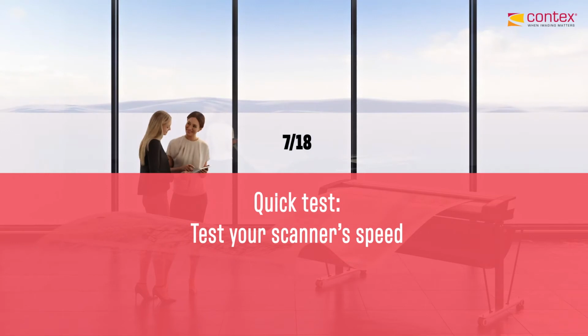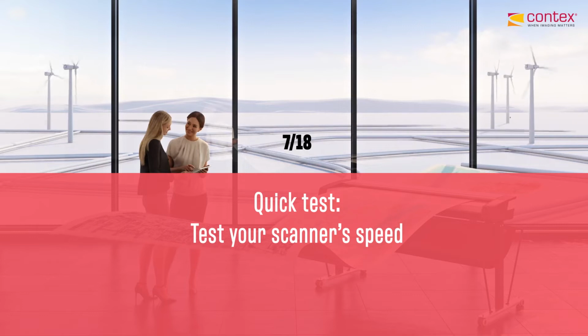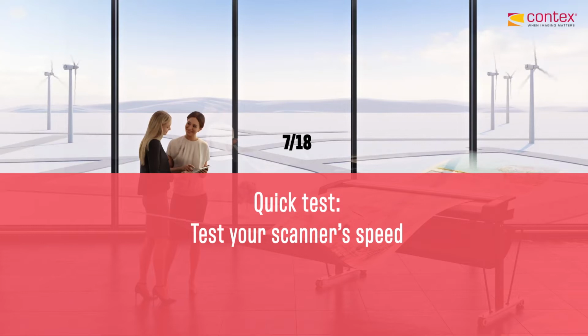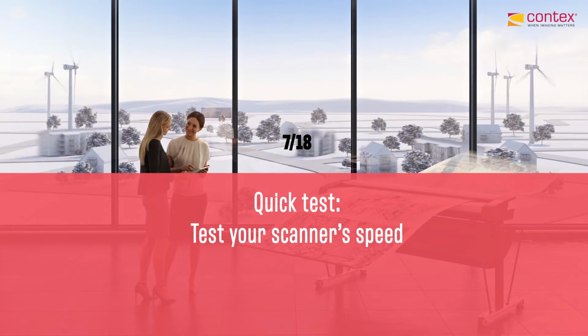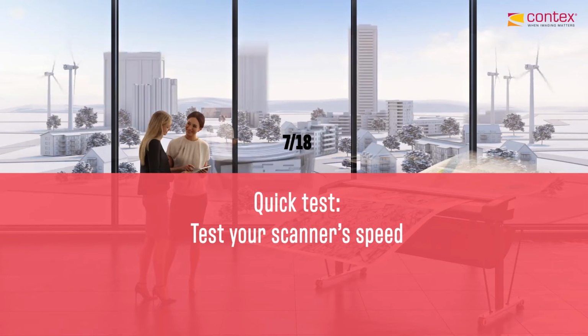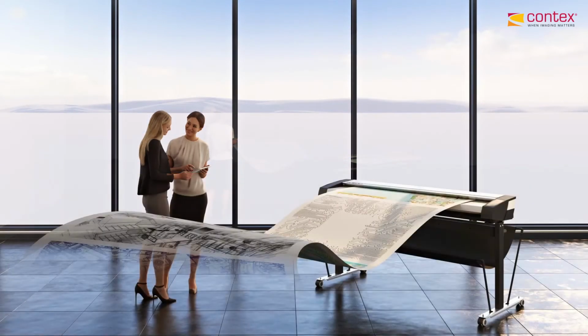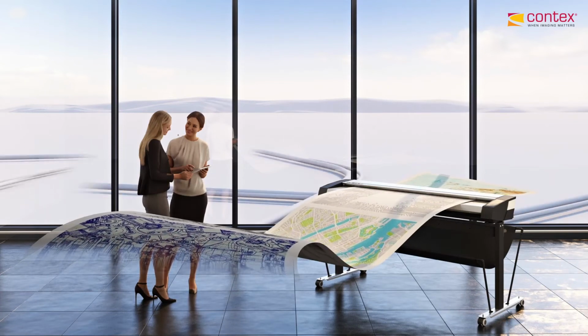You should see the scanner run without stopping. Gotcha. And if it does, then this might be another issue. Yeah, it's something else to look at, maybe a buffering issue once it's trying to write the files to, say, the hard drive in the computer, that type of thing. So that's a good troubleshooting test, to do that scan at 200 DPI, TIFF uncompressed. Yeah, it takes all the algorithms out of the mix, and is basically dumping raw data from the scanner to the PC. So it's a great test to confirm that things are running at the right speeds.